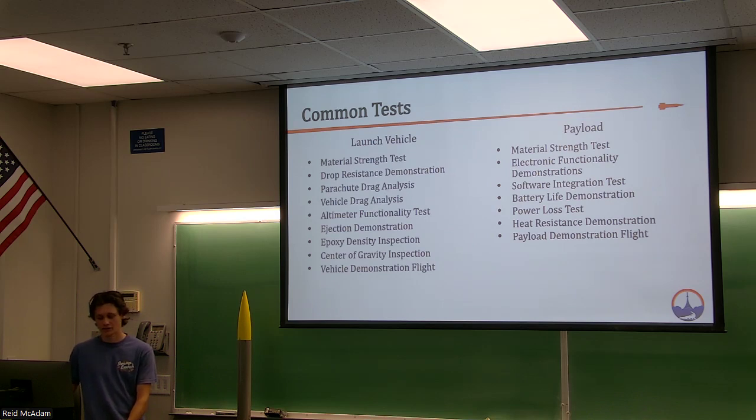Then you've got epoxy density inspection. And actually, I think that would be more of a test. You could pour some epoxy and figure out how much it weighs. Or you could weigh a little vessel, figure out its weight, then put in some epoxy, let it cure, and weigh it again and see how much its weight went up.